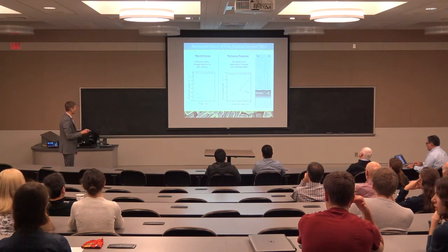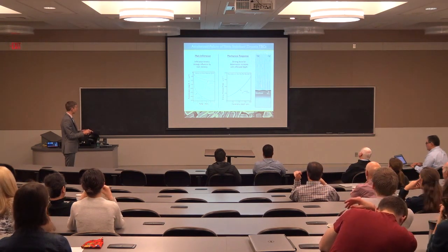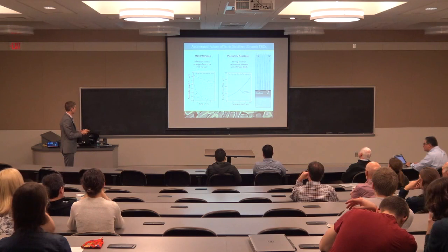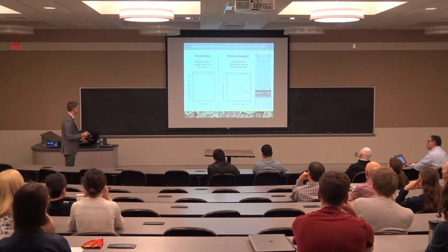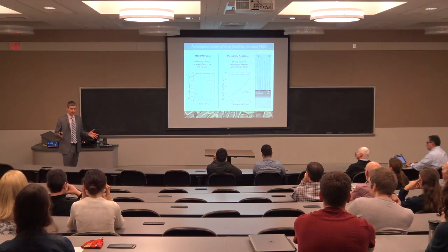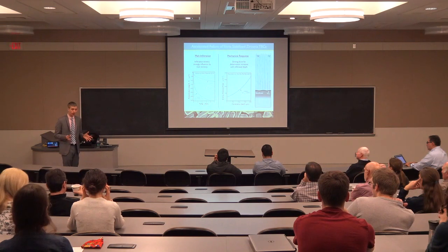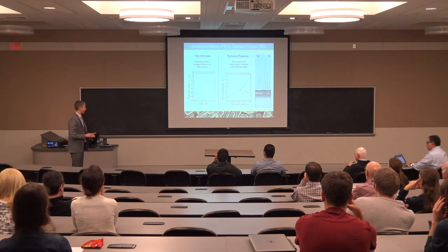So if we focus first on this TBC application where we have a segmented microstructure and the issue is the penetration. We can do things like calculate based on the viscosity of the liquid how quickly a coating might be penetrated, and we find that that's in the span of minutes to hours, much less than the lifetime of these components. So obviously, if the melt is there, it's going to penetrate.